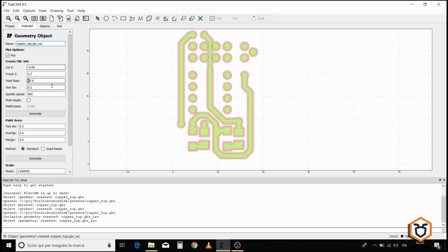The feed rate is quite an important parameter, and it is difficult to set with a perfect calculation, because it's true that there are some guidelines that tell us how to set the feed rate depending on the tool dimensions, the number of cutting edges and other parameters, but in reality it depends very much on the chuck rotation speed and above all on the rigidity of the machine. For now we usually set a feed rate of 90 mm per minute. You are absolutely free and encouraged to verify if 90 or a smaller or bigger number is better for your needs.